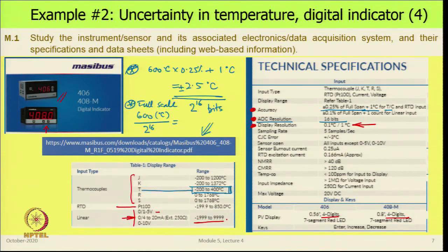So, as I was mentioning, many instruments in the real world which are used in process control and all that, would all have on the top of the instrument a transmitter which will convert the signal into an equivalent current signal and send it out.